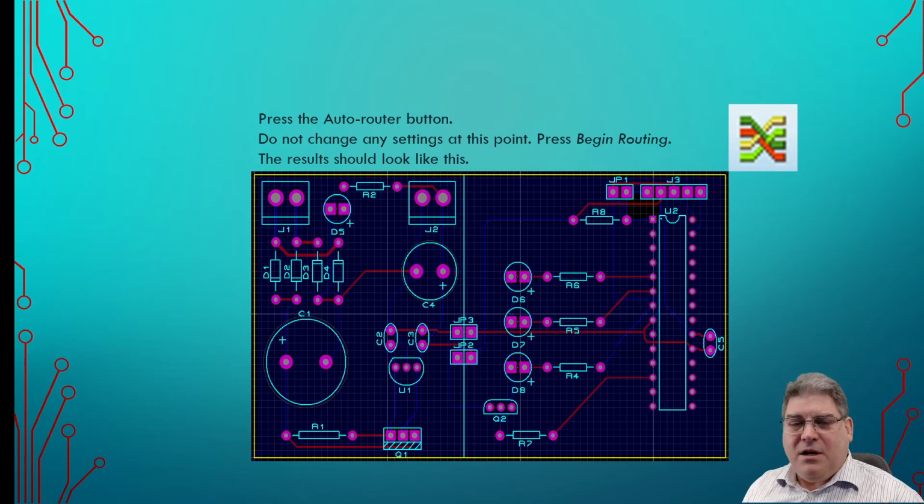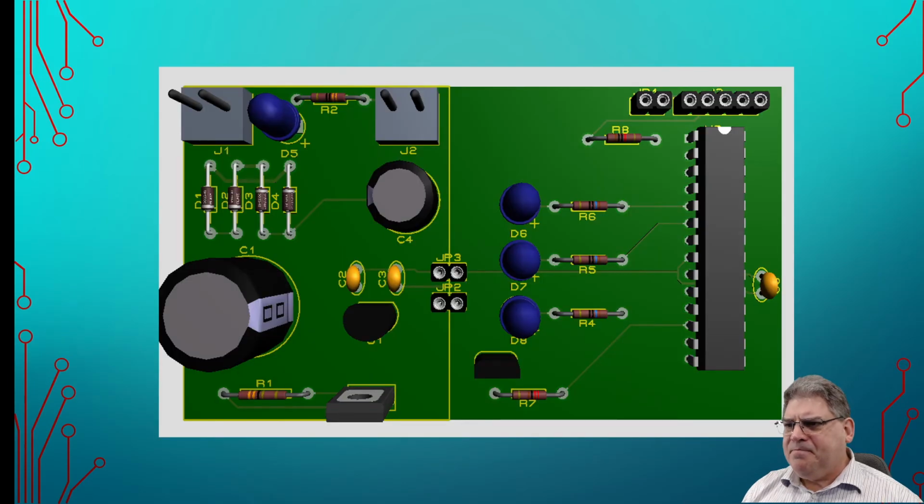And so what's our best plan here? The best plan is to make sure that important traces are laid down primarily by hand, and then you can run Autotrace on things that you don't really care about. And we'll circle back to that later.